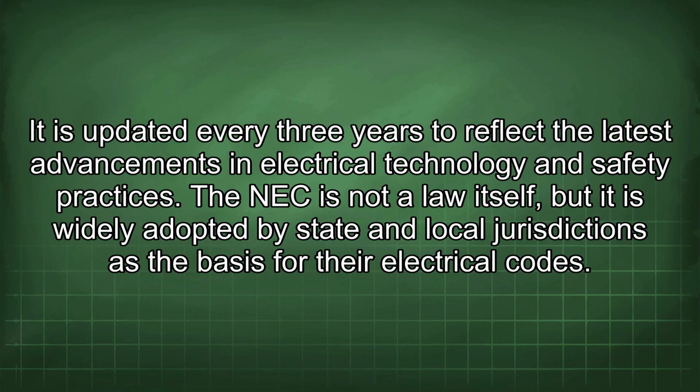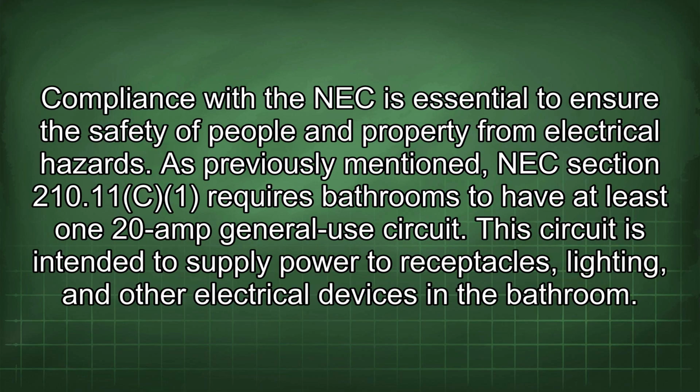The NEC is not a law itself, but it is widely adopted by state and local jurisdictions as the basis for their electrical codes. Compliance with the NEC is essential to ensure the safety of people and property from electrical hazards. As previously mentioned, NEC section 210.11(c)(1) requires bathrooms to have at least one 20-amp general use circuit.